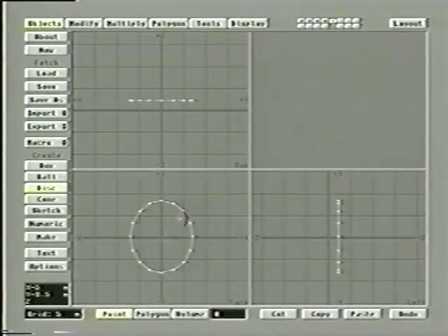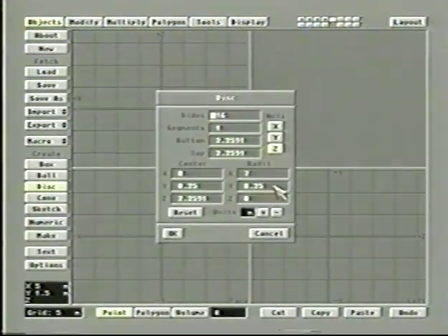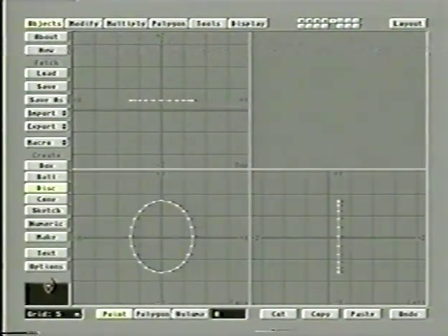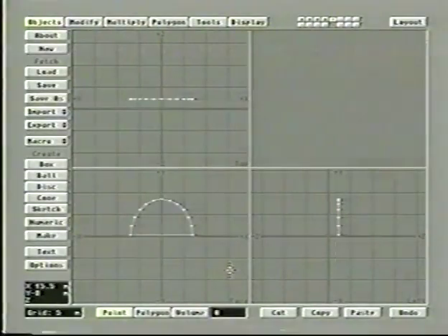Let me just undo it because I can see it's only doing 16 sides around. Let me just go to my numeric option and enter 24 for sides, just so it's a little rounder. Now again, we pick the bottom points, cut them away. There we go. Now, here's our basic tunnel shape.